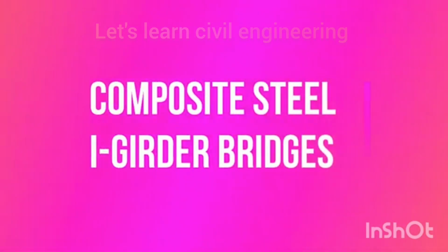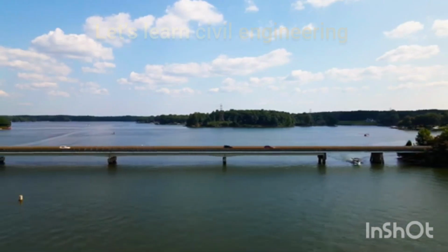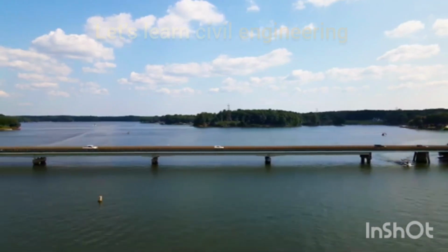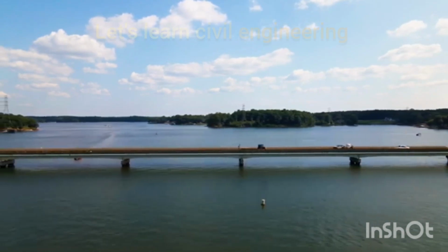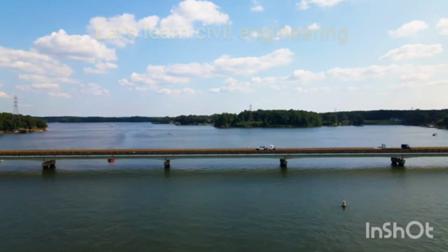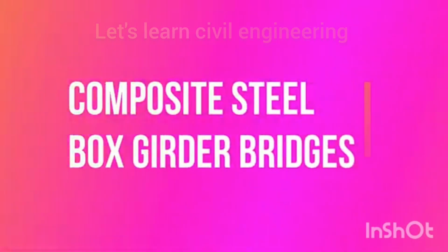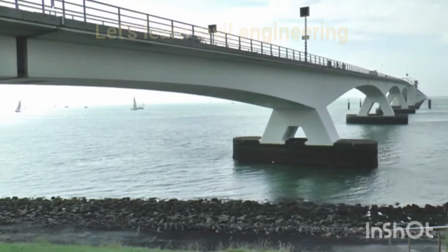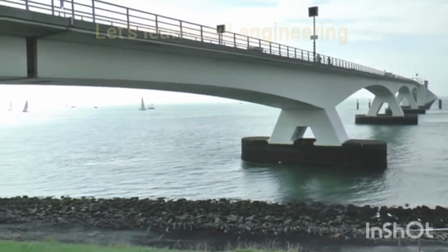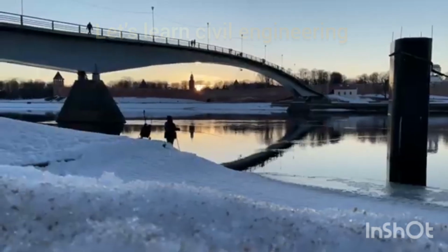Composite steel I-girder bridges. These bridges consist of a concrete deck slab over steel I-girders. Steel girders can be welded, bolted or riveted. Steel girders are connected to the deck using anchorages. Composite steel box girder bridges. Similar to composite steel I-girder bridges, these bridges are constructed using composite box girders. U-shaped steel girders are connected to the deck using anchorage struts.